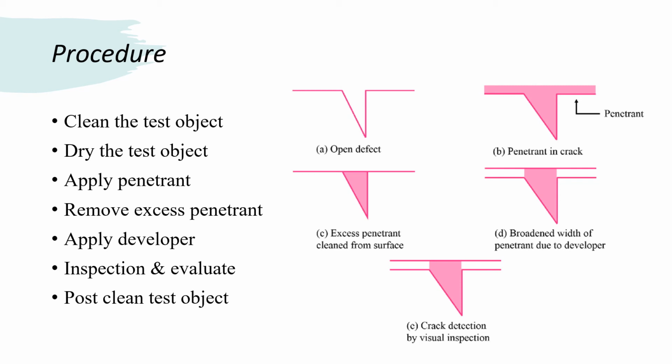The dwell time, which is the amount of time required for the penetrant to move into the crack, will vary depending on the crack size and shape characteristics, and also the environmental conditions such as temperature and surface inclination. Application of penetrant may be achieved by dipping the component in a bath of penetrant liquid or by spraying or brushing. A minimum dwell time of about 20 to 30 minutes may be allowed after penetrant application.